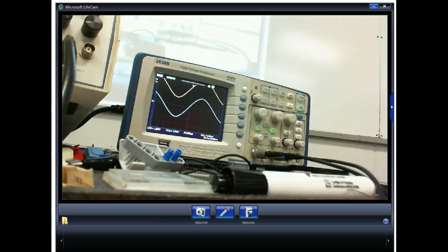Look things over. Visual inspection usually is the second one. If you got a problem, you look things over. Measure voltage. Then you start troubleshooting. If the voltage is okay, normally on amplifiers, we troubleshoot from the output back toward the input.